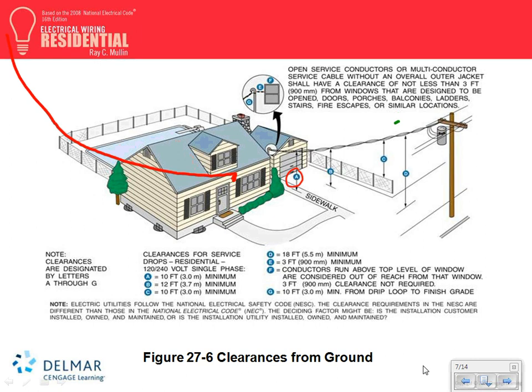Vertical clearances, building openings and so forth, overhead drop conductors. It's actually 230.24(B), vertical clearances, page 75. It will tell you that you need 10 feet minimum, no matter what. And then you have 12 if you are over residential property and driveways. It goes up to 15, and I'm reading this from page 75, the right bottom. It goes to 15 if the voltage is higher than 300 volts.